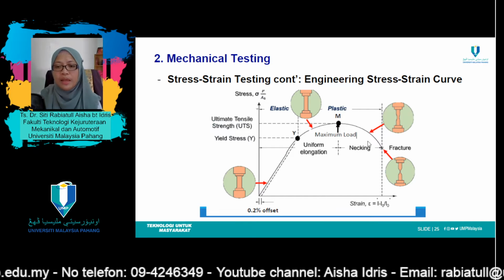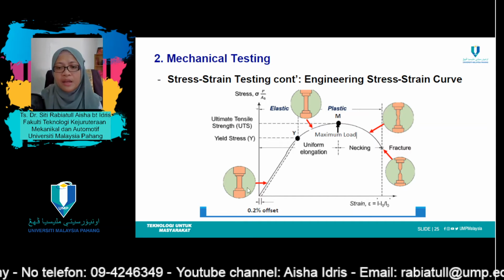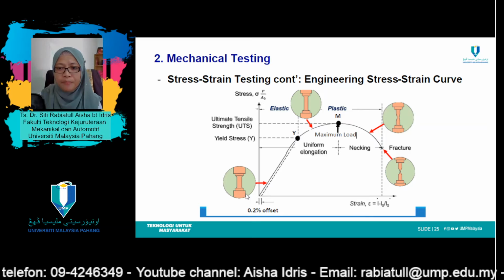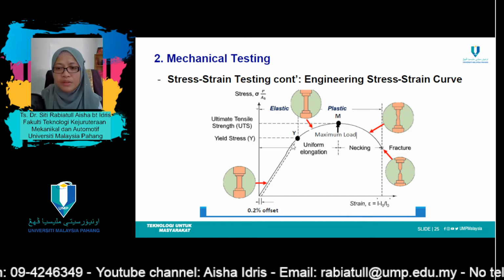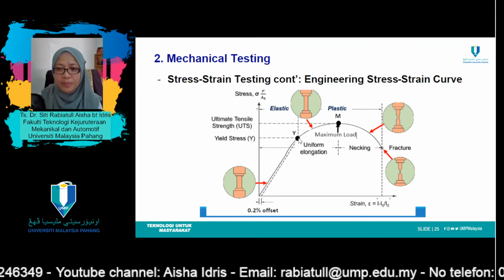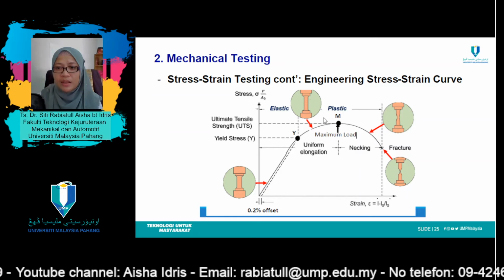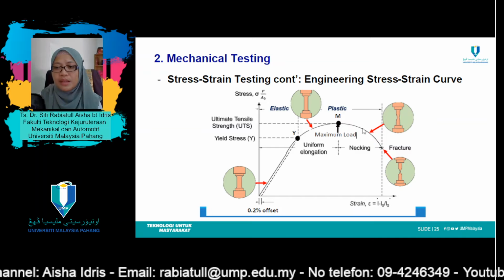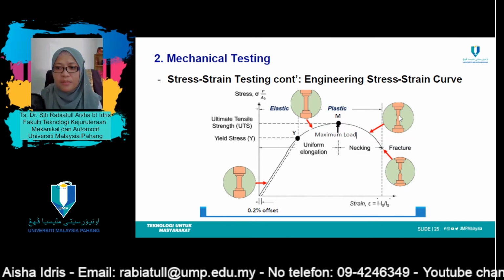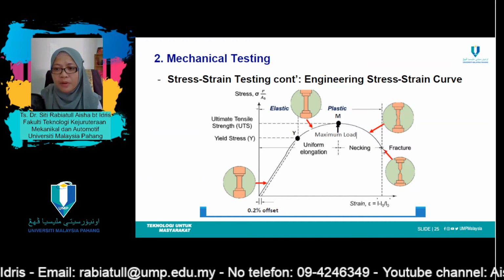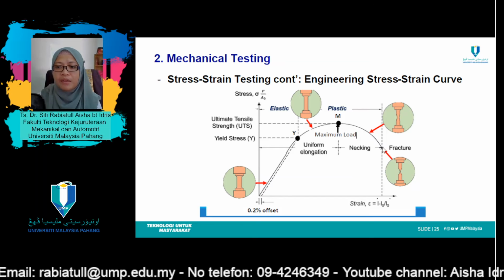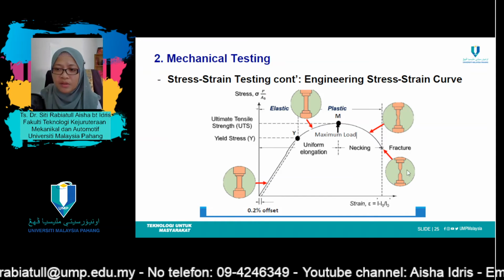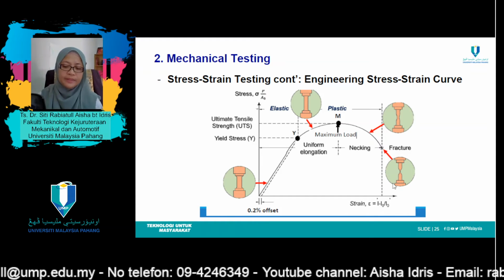Now let's look at the illustration. This is the original form. Then you give forces until this point where it starts to elongate. After that, after UTS, we will start to have necking over here before it breaks, and then reaching that point of fracture, it will break.